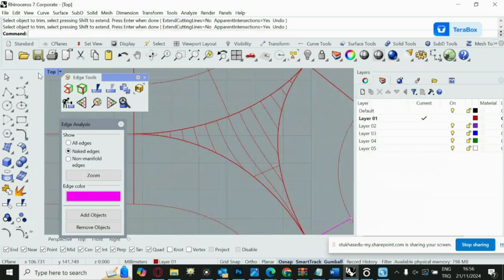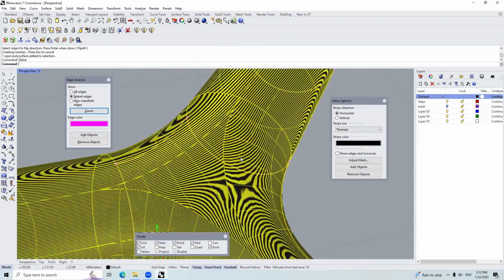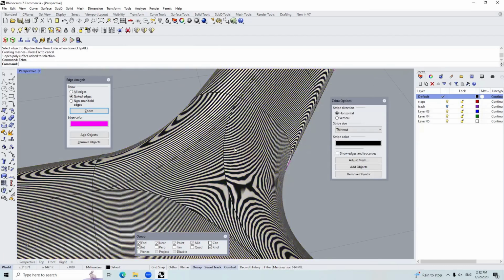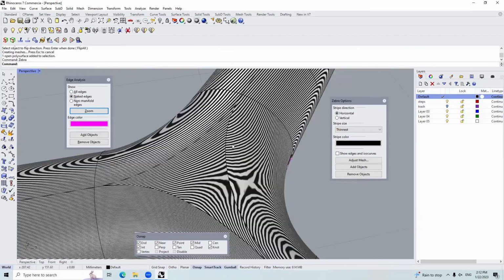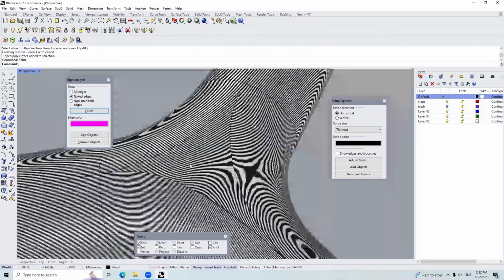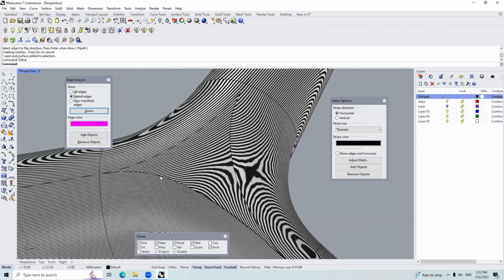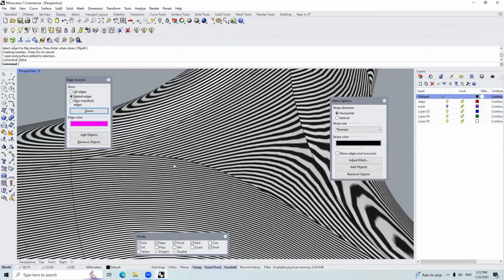Perfect, so after completing all of this, before doing anything else, let's do a surface transitivity analysis called Zebra. See the continuity of the surfaces and answer any problems we have. After the surface knitting process is completed, when we run the tool that shows the surface continuity named Zebra from the Analysis menu, it can be seen that there are some continuity problems. In order to fix the surface continuity problems, we have to do some procedural things.